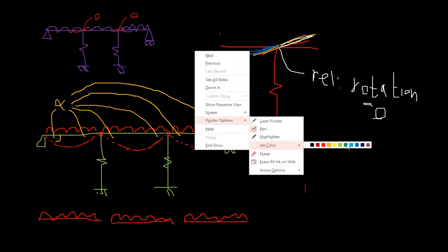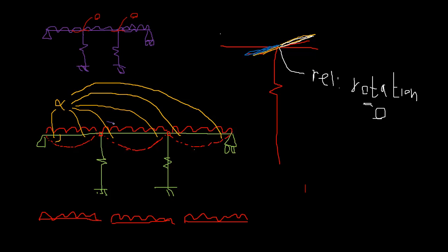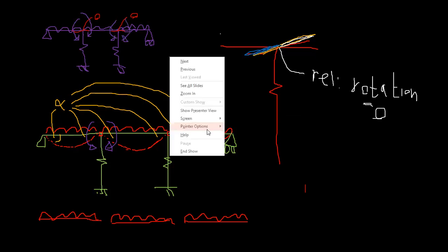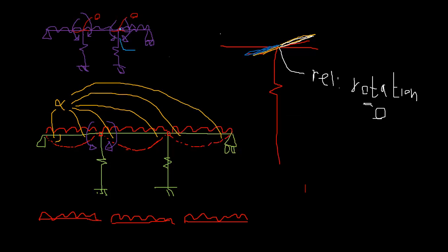I'm taking the bending moment, clockwise positive, okay? If I know this is already equal to this bending moment, and this is zero because in the primary structure there's a hinge. So if I want to find MB and MC in the original structure, I can find either one of them. I can find this, and I can find this, both. This is equal to the left side part, and the direction is opposite. That's it, right? So I will take clockwise positive.